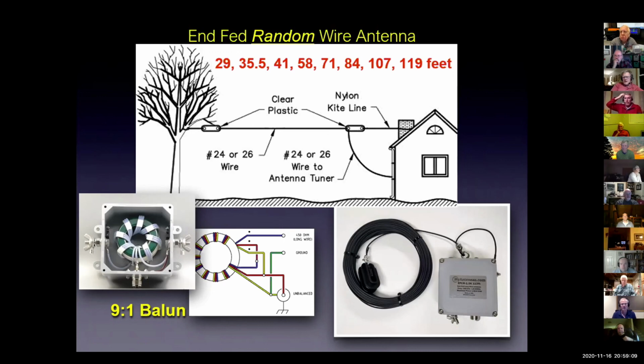Thoughts? Yeah, remember that there are two different issues going on here. One is an impedance that makes your transmitter happy, and the other is how good a transducer the antenna is in converting electrical energy in the antenna into EM waves in the atmosphere. And those two things are not really very related.